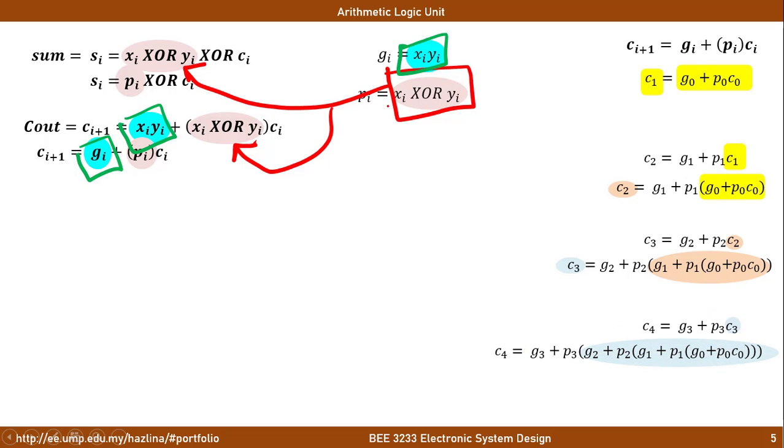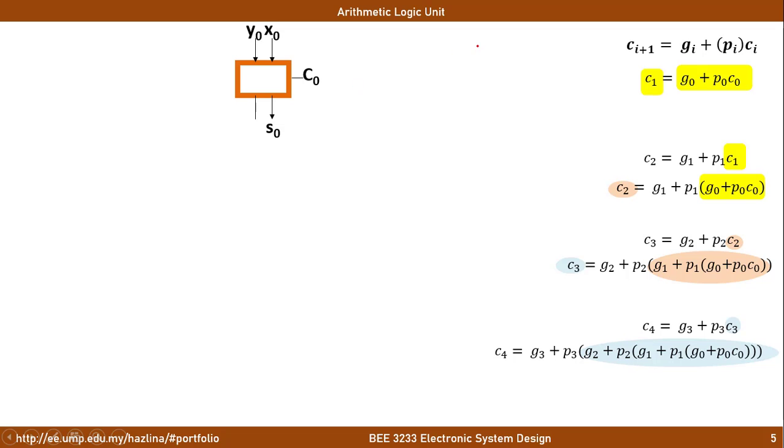Now, note that the difference between the first step that was shown earlier, the ripple carry adder, and the one that I've shown here is that the fourth bit of the carry in can be predicted at a second stage of addition, by predicting what stage 1, stage 2, and stage 3 are adding or are being derived from. So we can transfer this into a circuit. Okay.